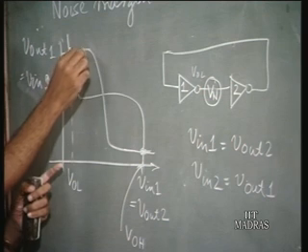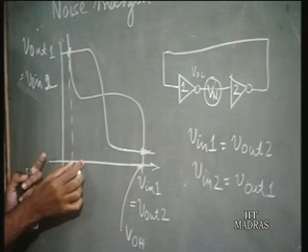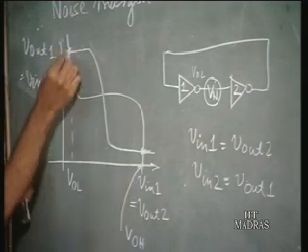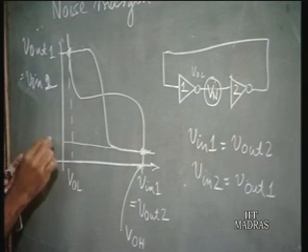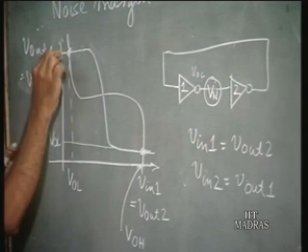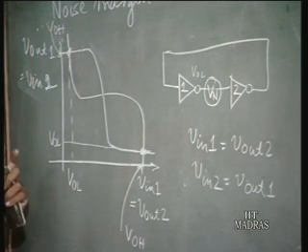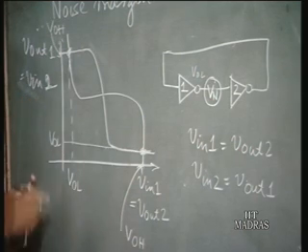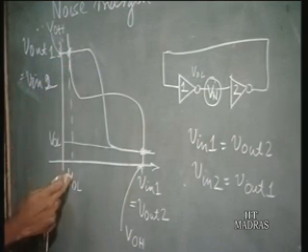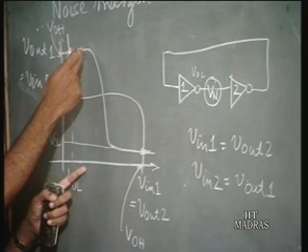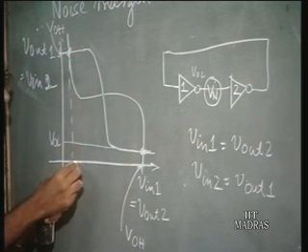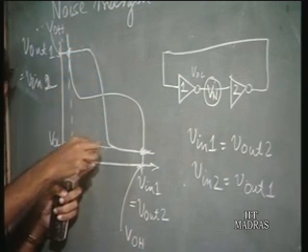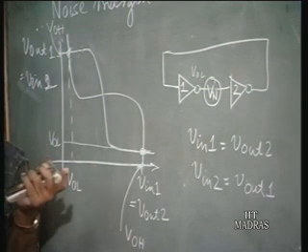So, even if the noise source is this much noise voltage, the output voltage is still equal to this high, this is VOH, this is also VOH, this is also VOL, this is also VOH. If you look at it this way it is the same. Now, when the input voltage changes, it is still almost close to VOH, but if this input voltage changes by a lot, then the output voltage may start to fall, and then only it creates problems.